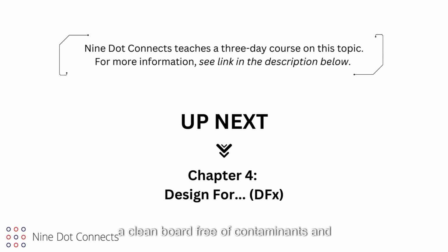Soldering demands a clean board, free of contaminants and oxidation. The soldering profiles are the temperature zones the PCB will be subjected to, in order to reflow the solder, without displacing the components to be soldered. The profiles are further defined by the selected solder paste. Gerber solder paste files control where the solder paste is to be dispensed.